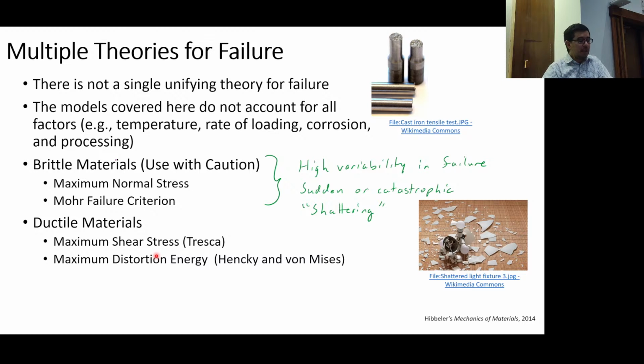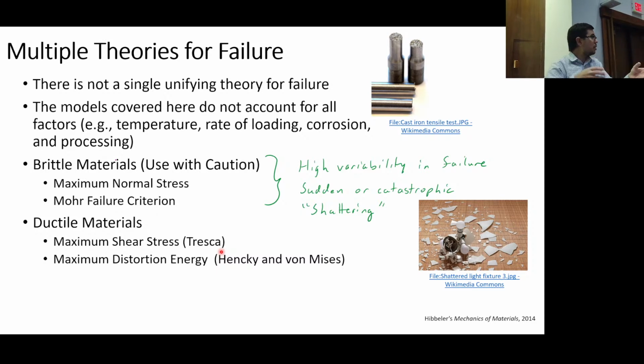So the radius of the Mohr circle for maximum shear stress in uniaxial loading, right? The radius is going to be what, and we're talking 3D, right? Because you have a sigma 1 and sigma 2 and sigma 3. So you have sigma 1 of a significant value under uniaxial loading. Remember, uniaxial loading, that's the tensile test. All right? So there's a sigma 1, and then what? Sigma 2 and sigma 3 are 0, right? They're just 0 because I'm stretching in one direction and I'm not stretching in the other directions.